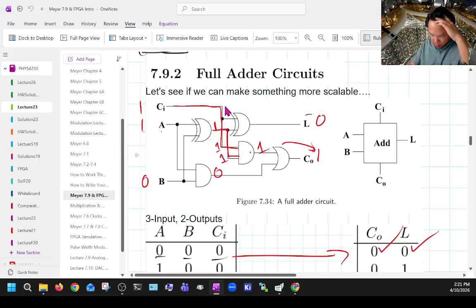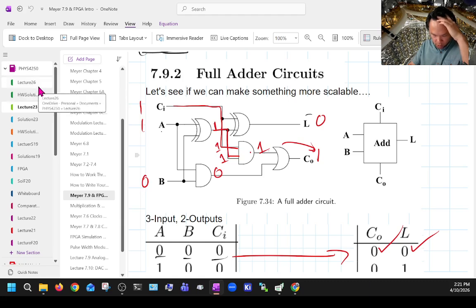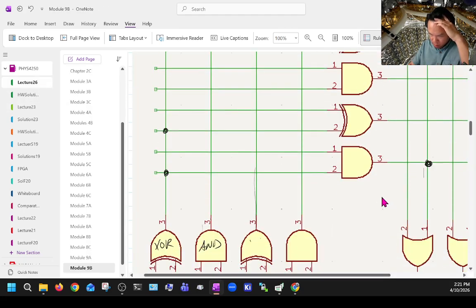Okay. Oh, it's the carry in. Okay, so we need a carry in wire. So let's make this wire carry in. Okay, and then this just goes straight, no connections required. And that fixes this. Now we know the input here. And I think that carry in also goes to this XOR gate.